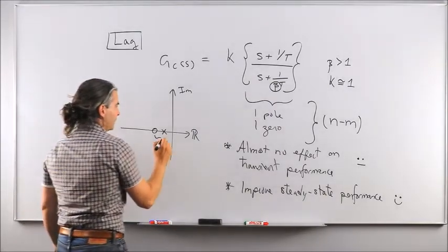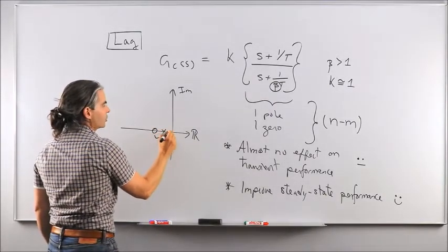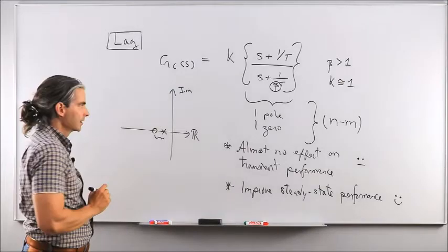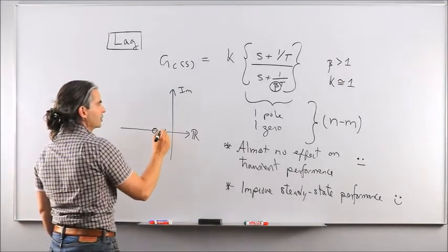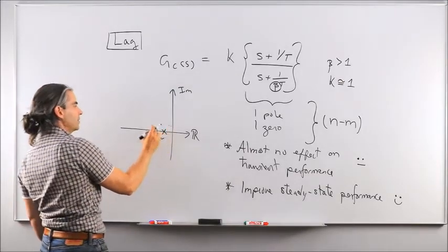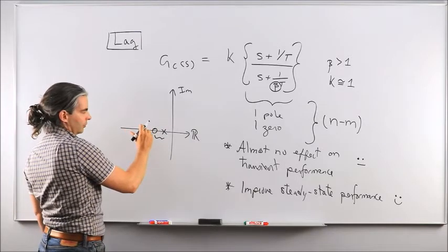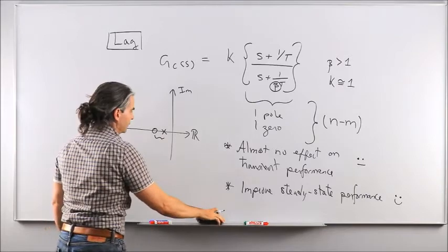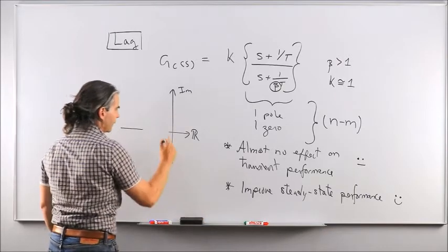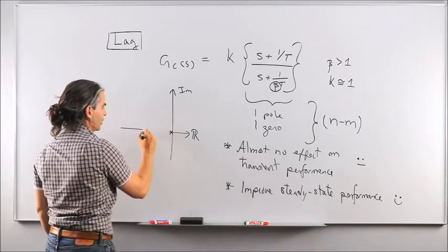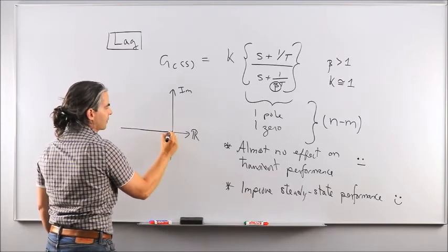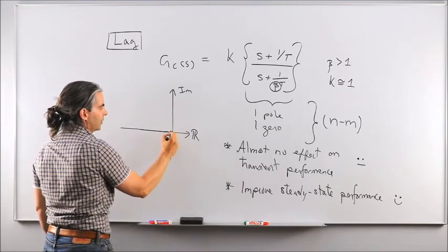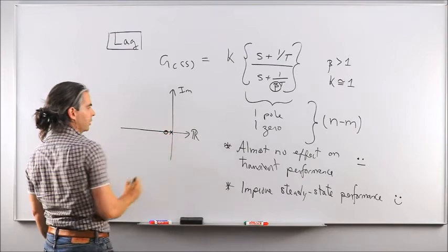But because we're going to set this pole so close to the imaginary axis, that will allow us to put the 0 beta times further to the left. Yet because the pole is going to be so close, 5 times or 6 times this very small distance will end up with a 0 location here.